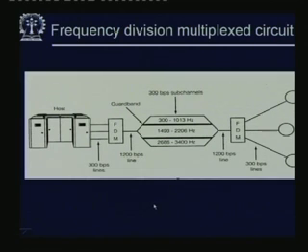Okay. So, here is another diagram. Let us say you have the host and a 300 bps line, a number of 300 bits per second lines being multiplexed to a 1200 bps line. And then there are some guard bands. Maybe 300 to 1013 hertz is one, 1493 to 2206 hertz is another line, and 2686 to 3400 hertz is another line. These are the 300 bits per second sub channels, and you have the guard bands in between. On the other side, again you have this multiplexer demultiplexer which takes it to different users.